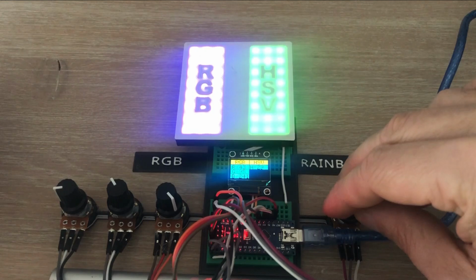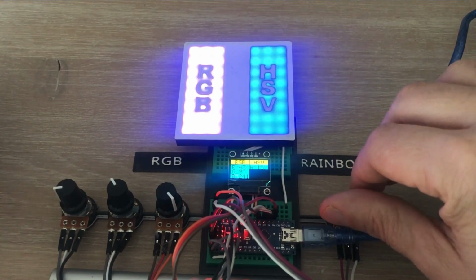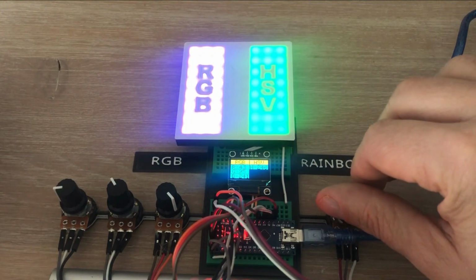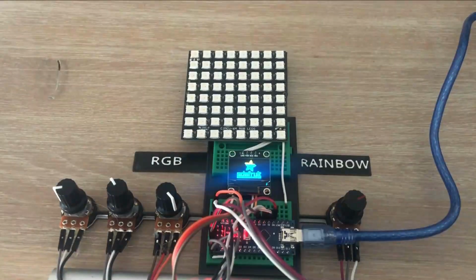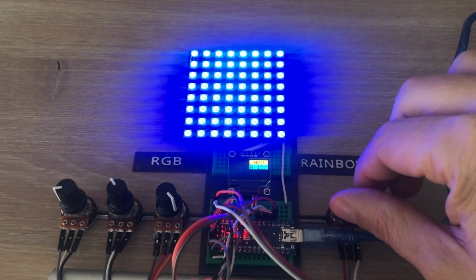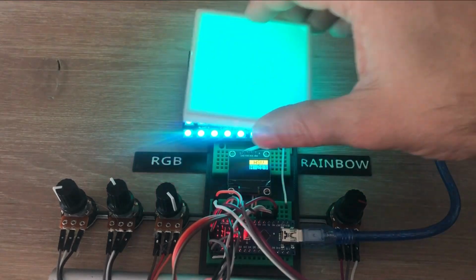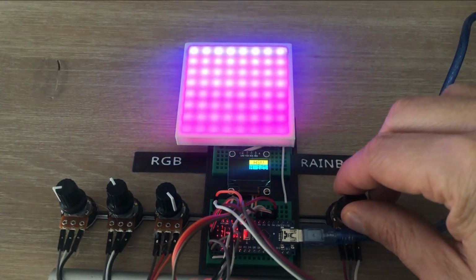You immediately see the difference. All colors are nicely saturated. Those 255 colors are all you need for your LED strip projects. With HSV you can also achieve nice color transitions. You'd have real difficulties doing the same thing with RGB color model.